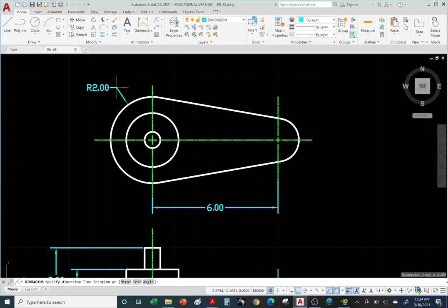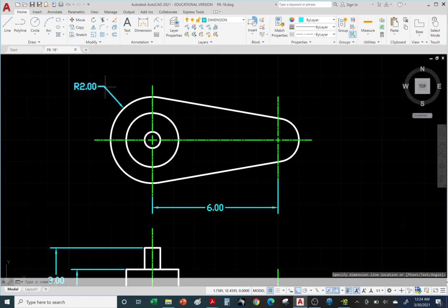One problem you may have as you're locating your radius is you may want to have ortho off and or object snap. Sometimes it doesn't move where you want it. As you can see, it's moving all over the place. So if you're having issues locating your dimension, you can always turn off ortho or object snap. Let me click out here. Later on, if you try to relocate it using the grips, it's not going to cooperate because we have ortho on. It's trying to only move vertically or horizontally. So you can turn off ortho and see now you have more freedom.